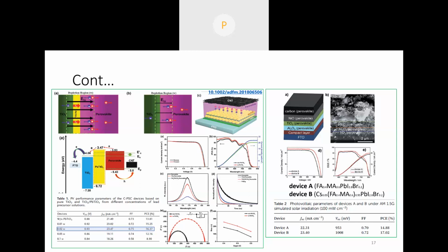In this case also they found that by adding one extra layer, you know that the difference between PN and PIN is that in PIN the depletion width increases. So they checked the effect of increasing the depletion region width and the built-in potential of your solar cell on the device performance. And they found that if you increase the depletion region width, your VOC will directly improve. Similarly, your JSC and almost all the factors are improving, because they achieved a 75% fill factor with this.